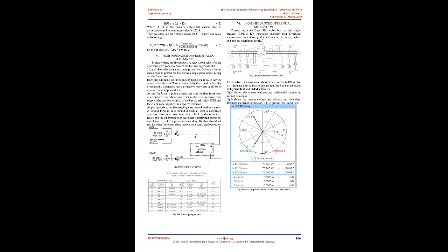We shall select the maximum protection voltage from the data sheet so that the relay system insulation can withstand it, as per Table 2. For example, most LV equipment can withstand up to 1 kV.